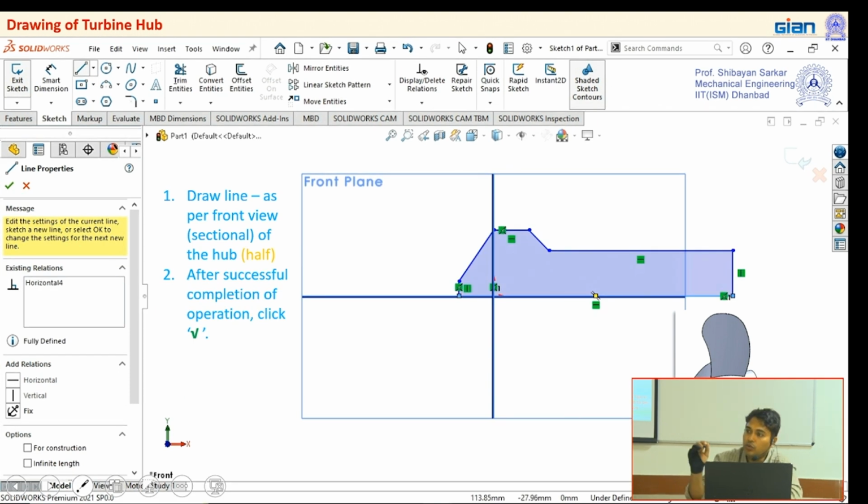And you should close your drawing properly, which is very much required, because I would like to make a plane like this. This plane will be rotating about the axis of rotation, and then it will form a solid body which will have a cylindrical shape. Because of this, it will form some grooves. Here it will be a groove, here another groove, here another groove.